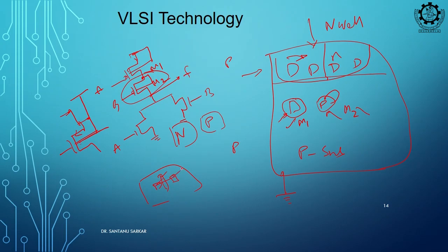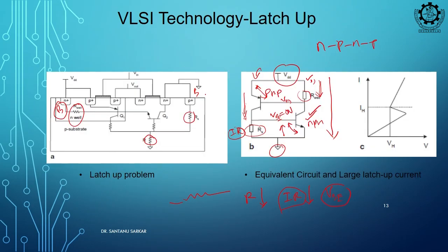Another fourth terminal is there, when you are doing the physical design, the fourth terminal should be there. The fourth terminal is generally one P tap and one N tap. We use some P tap material, we place it here which acts like a connection for the P well.